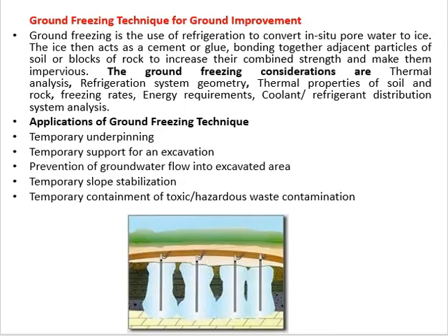In freezing technique, the pore water is converted into ice. The ice binds the soil particles and increases the strength. This method is used for temporary purpose during the construction stage, especially to prevent the walls of excavation from collapse.